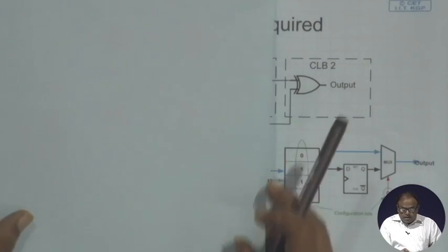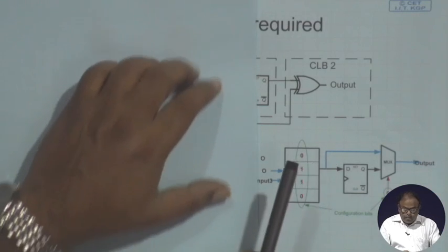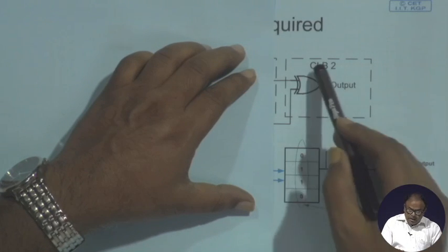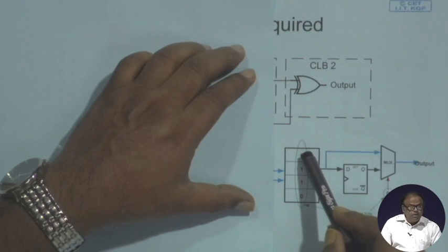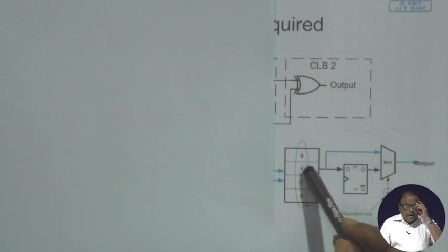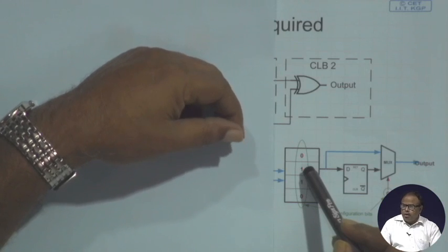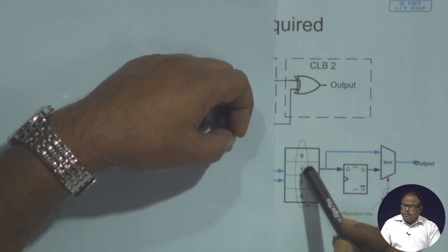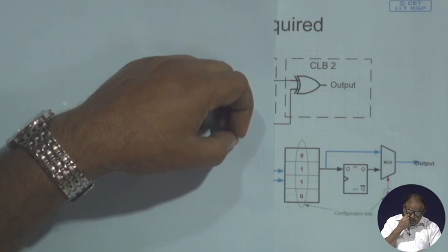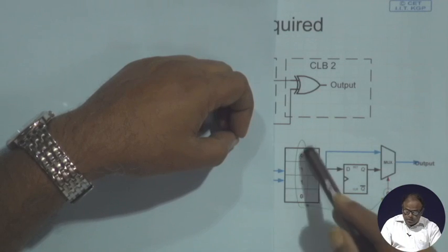Again, coming to this circuit, here I have to implement just the XOR gate, and the XOR gate can be implemented using the truth table 0 1 1 0, because it will be 1 only when not A and B, and A and not B, all right. So, either one of them will be true; both of them cannot be 1 or both of them cannot be 0.